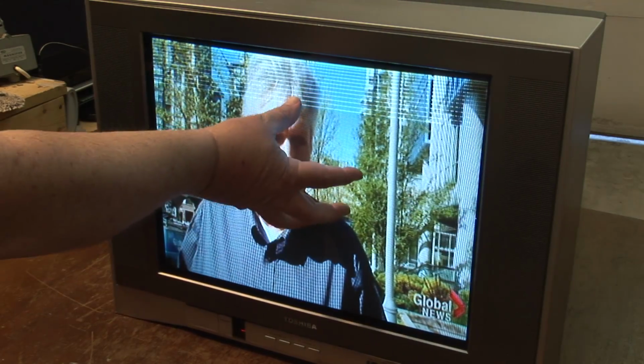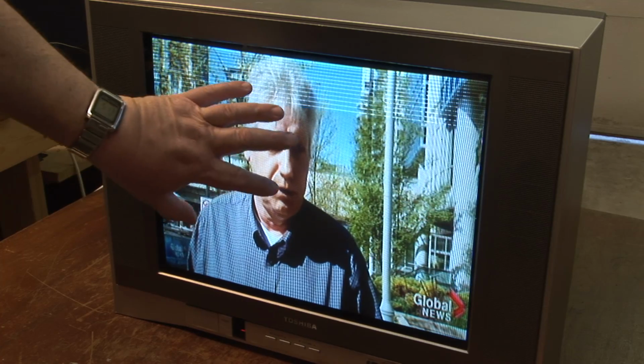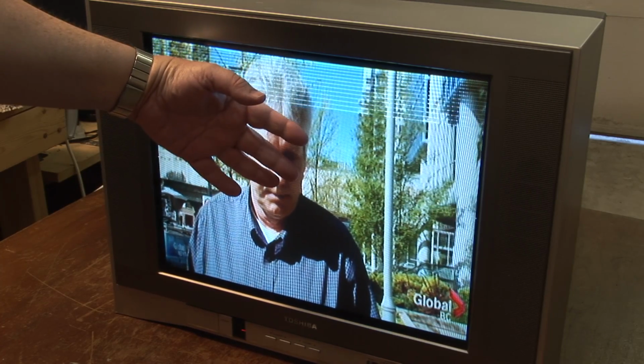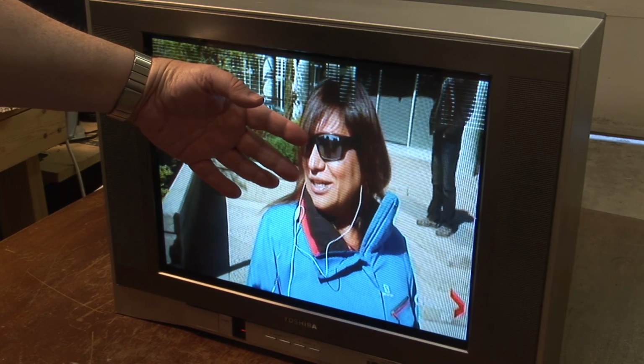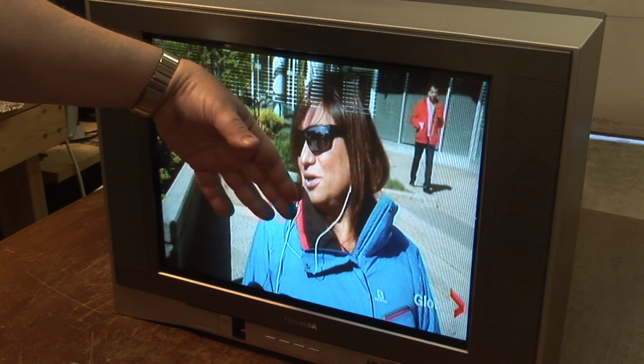It's actually line by line, but the persistence of vision causes this to look like a picture, but it's actually not. And a CMOS camera will actually capture that scanning line, whereas with a CCD camera, the shutter stays open for the entire 1/60th or 1/30th of a second and captures the entire frame, more like the eye does. So we're back to the future.